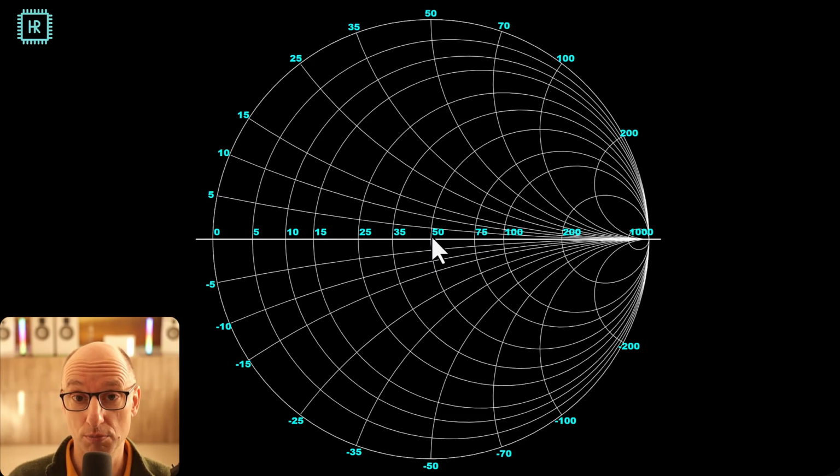And this frequency appears to happen at a quarter wavelength. So the idea is we're making a 180 degree rotation here, while the length of the trace is only a quarter of a wavelength, which is 90 degrees. The impedance moves twice as fast around the Smith chart as the length of the transmission line you use, and that's because the signal has to go there twice. It has to go through the transmission line to get to the load and then reflect back, so that's 2 times the length.